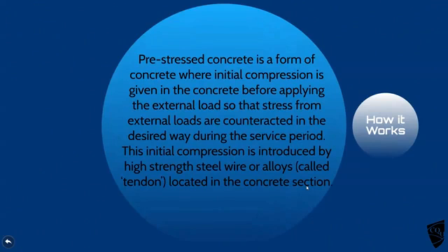Pre-stressed concrete. Oh, I've had fun with this in the past. It's concrete where an initial compression, a squeezing of the concrete, is given before applying any external load to it, no weight to it. So stress from the external loads is counteracted by the applied compression, the squeezing.